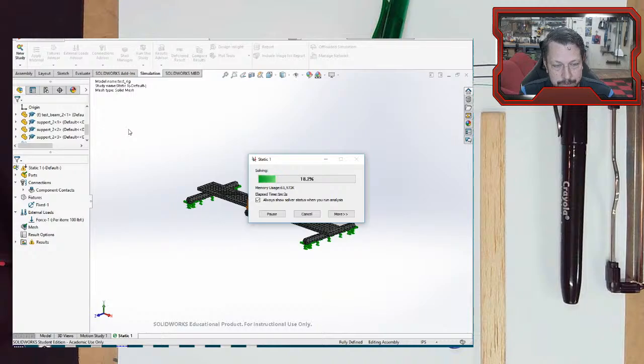This is not one of those, but you can still have hours of simulation time and then find out that you had an error in your geometry or something like that. Hopefully we will get this one to resolve, but there's a big difference between those surfaces sliding past one another versus them just being bonded together. As you can clearly see, the bonded one was almost instant.